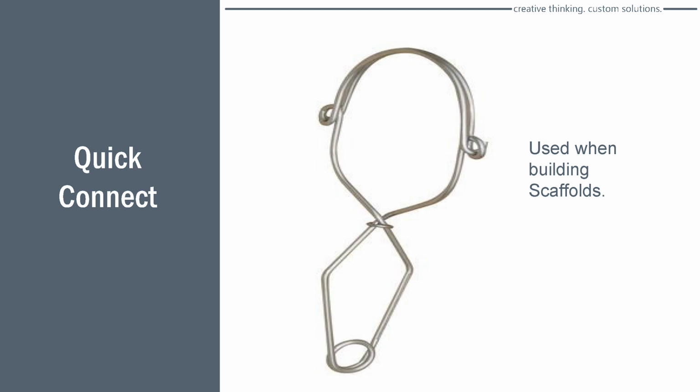This is used a lot of times in scaffold building. I've seen scaffold builders use this a lot. It's lightweight. It has been tested. The documentation is there. The only thing is they usually connect this to the handrail of the scaffold. Now, to be honest with you people, the handrail on the scaffold is not rated for 5,000 pounds. Usually they're about 4,000, 4,500, something to that nature.